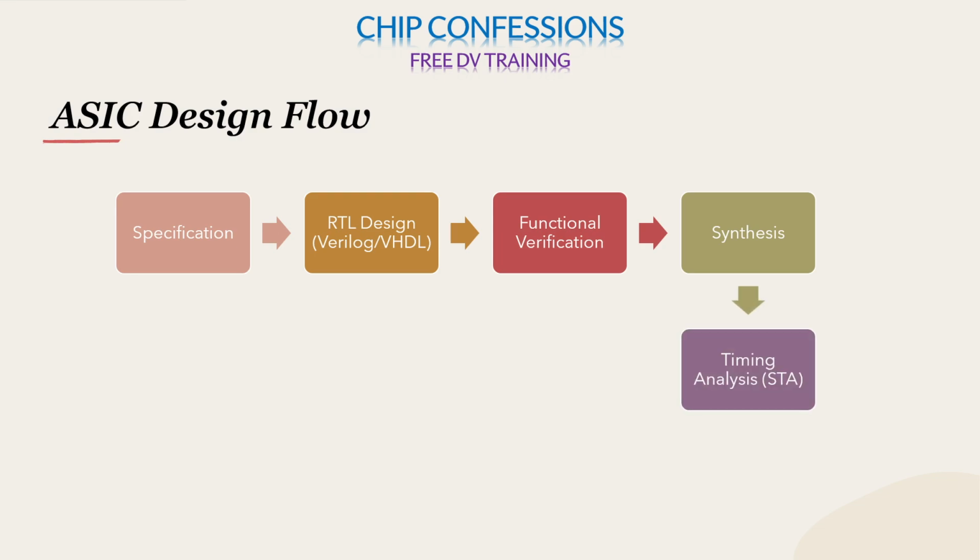Later on we will do timing analysis. Once the logic gates and everything are done, then we have to check the timing, whether the design is meeting the timing requirements such as speed or clock delays, whether everything is fine or not. That we will be checking at STA, because we have to ensure the data is moving correctly across the chip.